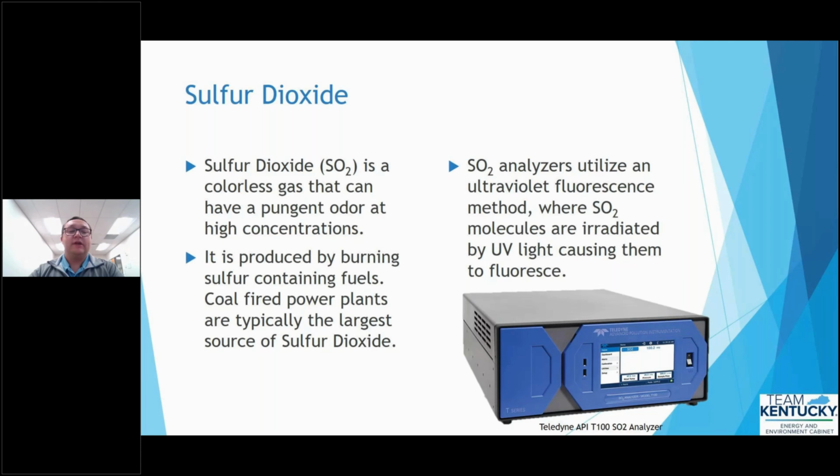We operate the Teledyne API T100 SO2 analyzer. These analyzers use ultraviolet fluorescence, where the molecules of the gas are irradiated by UV light, causing them to fluoresce. That light emission is then measured and correlated to known concentrations to provide a measurement.